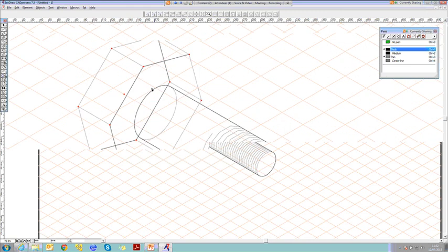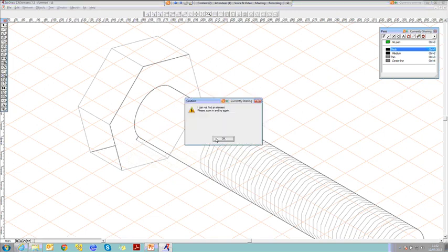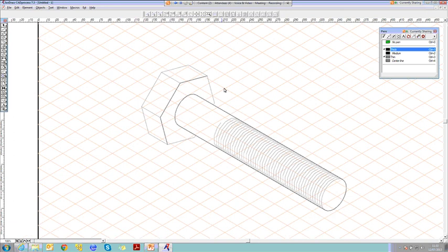And we've got some nice intelligent tools for removing lines, so IsoDraw will understand the lines that it needs to remove when selecting the line. So all you do is select the line and hit a keyboard shortcut, which is already programmed into the software, and it will figure out which of the lines it needs to remove. So for example, you select the back line and hit the F6 key, it will automatically understand that it needs to remove that back line.